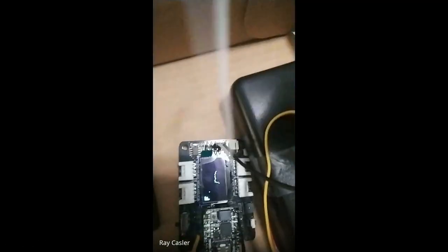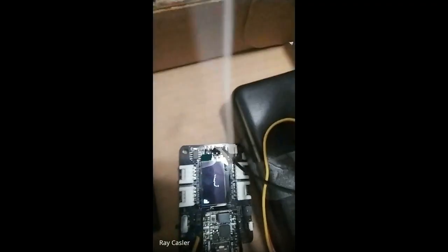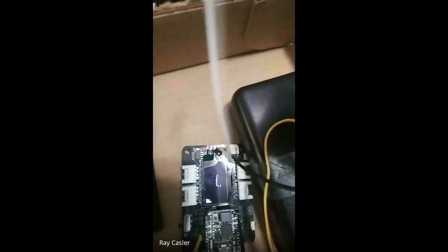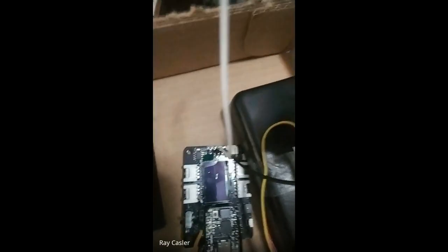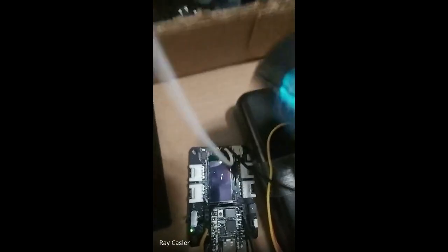So basically there are three 30-degree zones. 30 degrees facing forward, 30 degrees to the left of that, and then 30 degrees to the right of forward. And so it looks at all three zones and sees if there's an obstacle in it. And if there is,